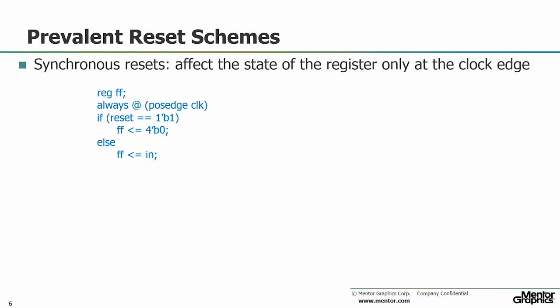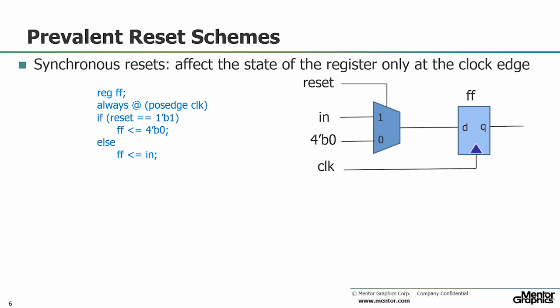This is a simple Verilog RTL for a register FF, which is inferred as a register having synchronous reset by the synthesis tools. The output of the register FF will be changed only with the passage of clock. To get the effect, the reset should be wide enough to be captured by the next passage of the clock CLK.